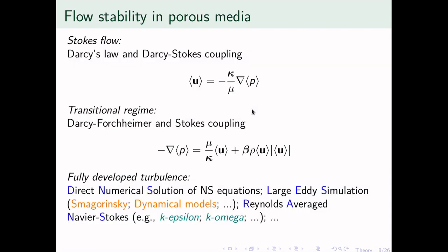When we talk about stability of flow in porous media, when we talk about slow flow, which would in theory be governed by the Stokes form of the Navier-Stokes equation, we ignore the time derivative of velocity field, and we also ignore inertial components. It's usually easier to generalize inertial components as non-Darcy effects or non-linear effects, because inertial effects are complex and there is a lot of other things involved in inertial effects. So we're going to call the inertial effects non-Darcy effects.